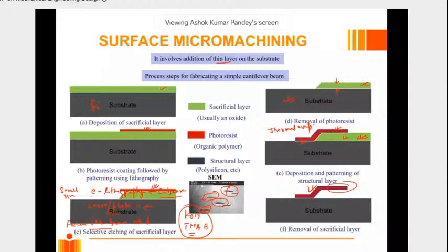So we need to be careful. We have to standardize the process so that such kind of thing doesn't come up, or for different types of beams we first need to check, using some process flow, what defects we may get, and by following the guidelines of that fabrication only we should try to design our sensors. Okay, so this is another effect that you see. And yeah, these bendings are because of the residual stresses. I took this slide from Professor Prem Pal, who is my colleague at IIT Hyderabad.